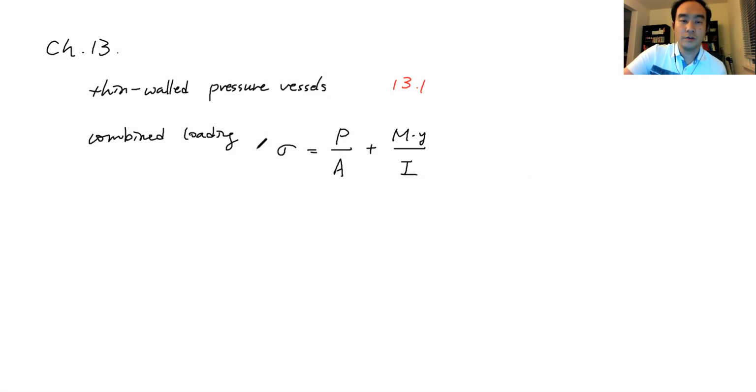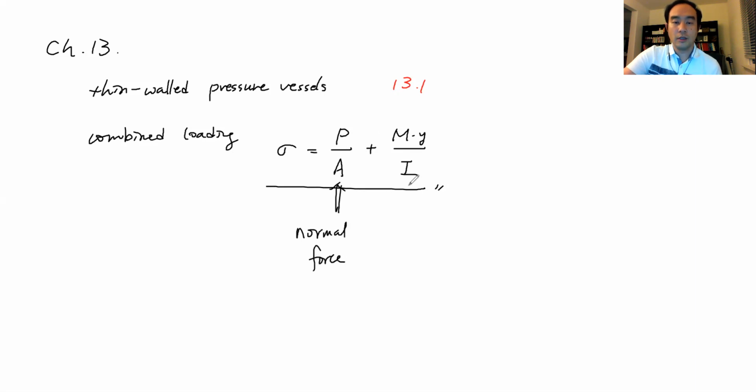So this is basically the main equation for finding the normal stress due to the normal force, and then this is the term due to flexure, the moment. Problem 13.2 would be a good problem to practice this combined loading.